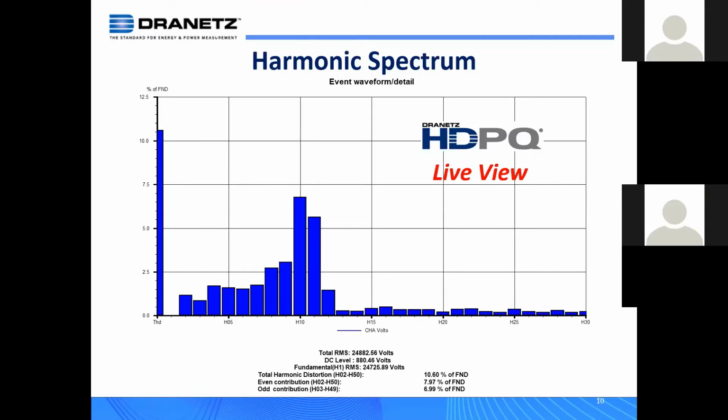So where do harmonics come from? They actually come from the loads that we plug into our systems, whether that be in a basic case just a basic computer load, or the PLCs we're putting into our manufacturing facilities, or our control facilities, or a data center with the electronic power supplies in our servers and all our networking equipment, stuff like that.